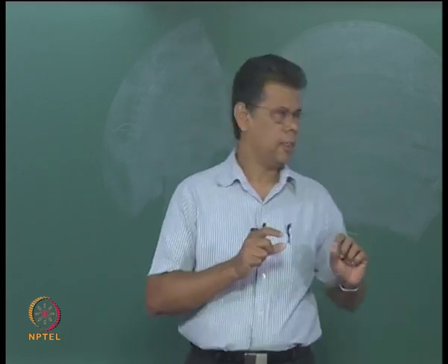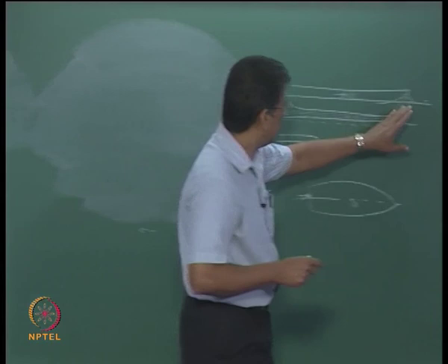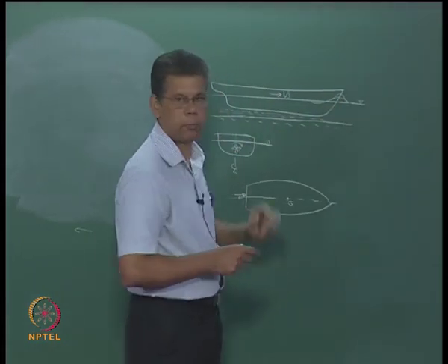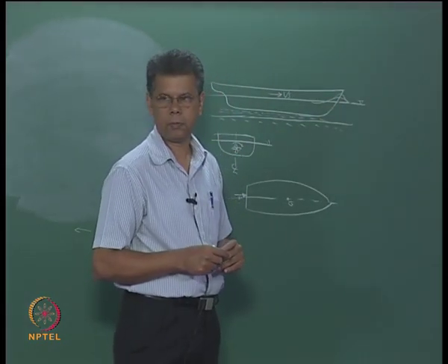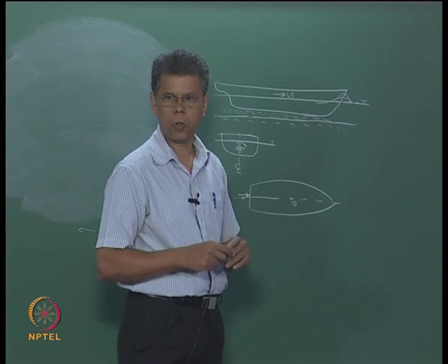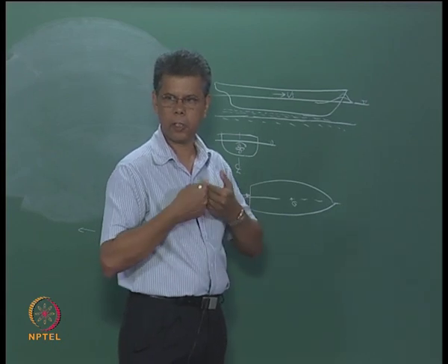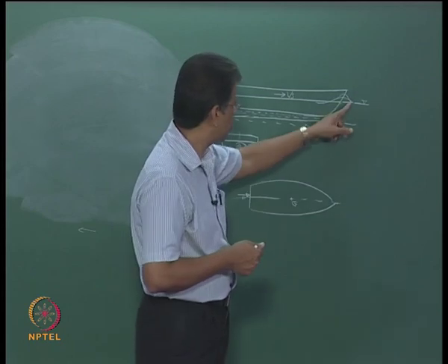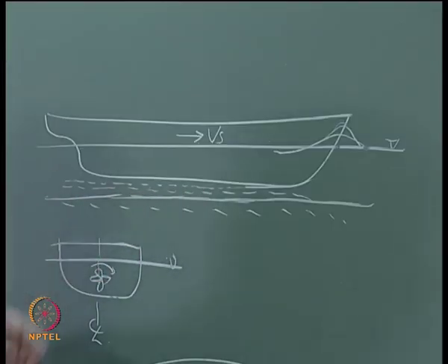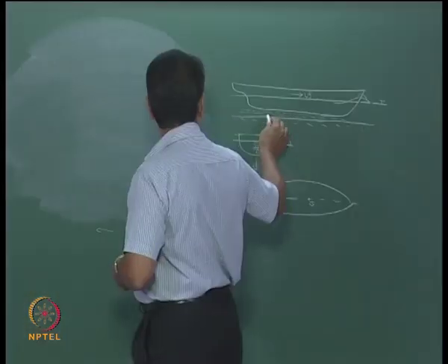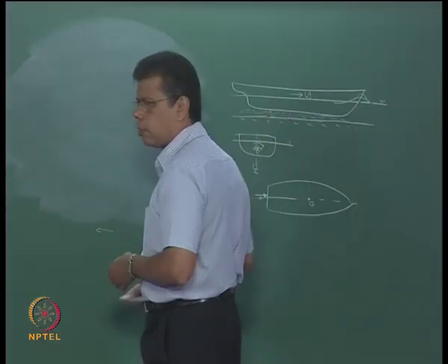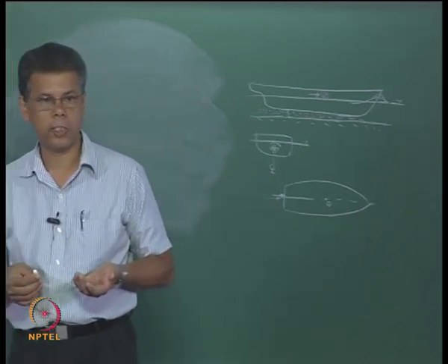Okay. So now the water here has to escape to this side. There is conservation of mass, it has to flow. So the same water, when it flows through, tries to escape through the bottom of the ship. First thing, due to the constriction, due to reduction in waterway itself, there will be an increase in flow, isn't it?